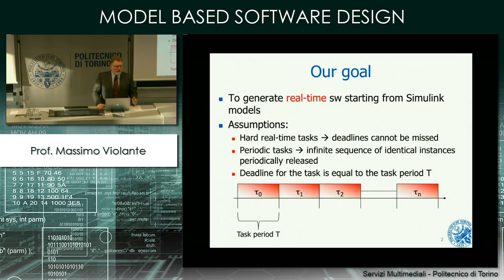This means that we will model the plant that we want to control, we will model the controller, then we will generate the code out of the controller model, either using algorithm export or full executable export. This is depending on the target platform that we are about to use. But at the end, whatever is the target, we want to generate real-time software.